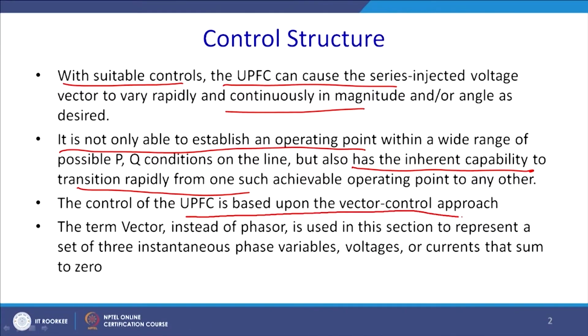The control of the UPFC is based upon the vector control approach. Since we take the magnitude and the phase of the voltage while injecting a particular voltage, for this reason we call it a vector control approach.